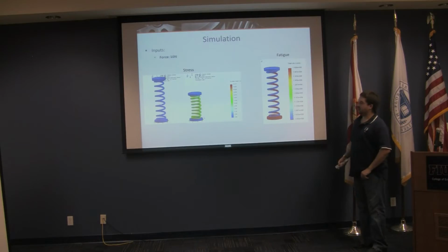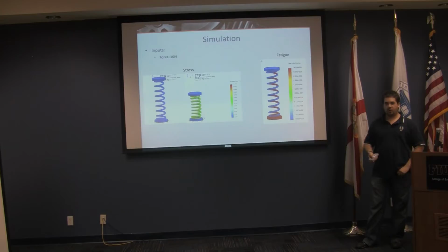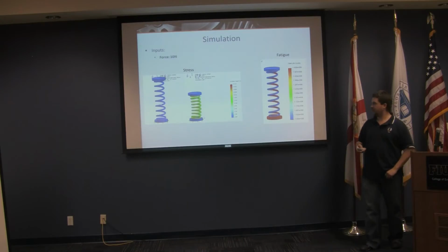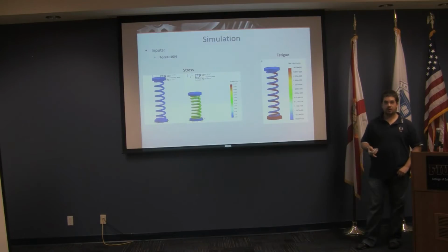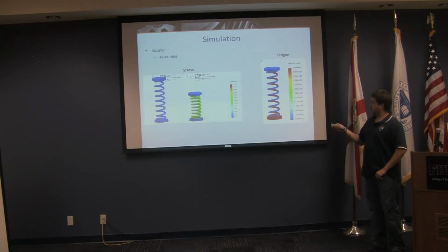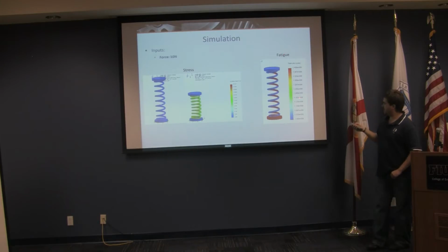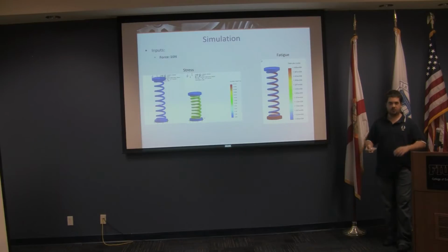As far as simulations are concerned, we found the nitinol model on SolidWorks. We're still trying to get all the proper material characteristics in order for it to function properly, as nitinol is not a linear acting material. It's non-linear. And we did stress analysis based on nitinol material as a spring in the 2 different modes. And we also did a quick fatigue study. Now we know that this fatigue study is based on, I believe, the steel curve is what we used. So it's not completely accurate, but we will find a way to intercept that. But this is just, you know, intermediate results right now.